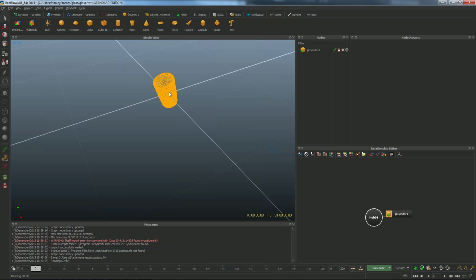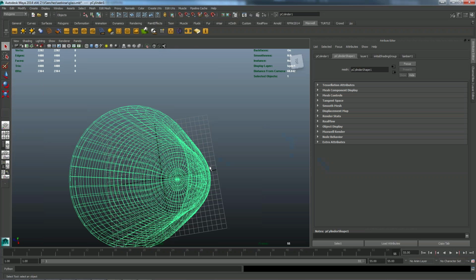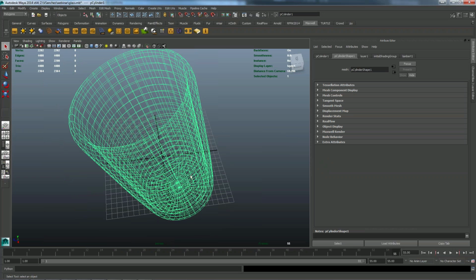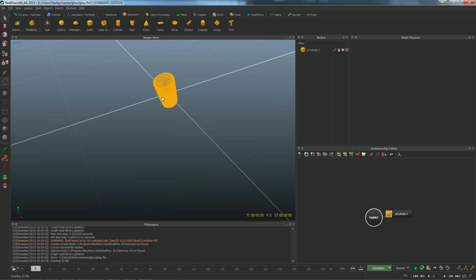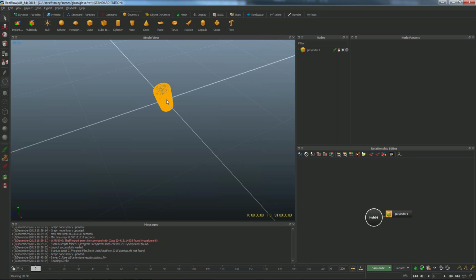It doesn't mean that I have to work exactly in real scale. This is really important. In this case, if you take a look at this, this is roughly about 8 or 9 centimeters, assuming this is 1 meter. But once again, working with this scale is really hard because it makes RealFlow perform a lot of computation in such tiny space, and it might affect RealFlow and become unstable, even crash. So I don't recommend you deal exactly with the same scale.